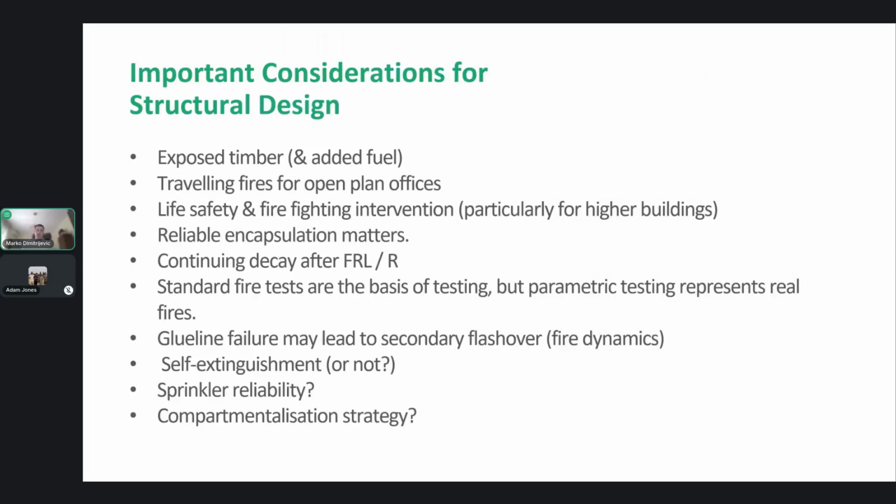It's good to first discuss what the important considerations are, because there is a bigger picture involved beyond just structural fire design. There is a question about exposed timber and how much we can have of it. That's pretty much the story for every timber project, along with how different services interact with each other and how fuel is added. There is another open question about traveling fire for open offices, then life safety and firefighting intervention, especially as buildings are getting higher and higher.